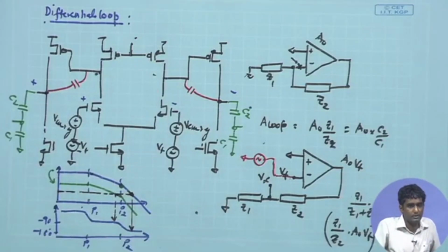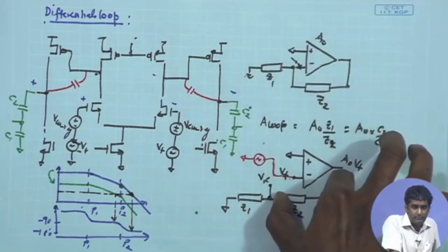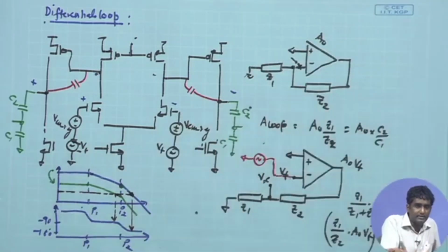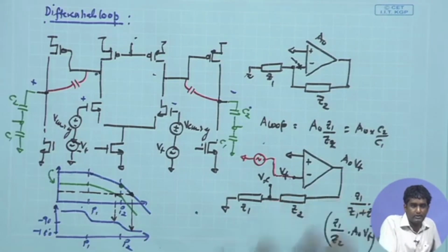How will RF affect the low frequency region, like you told now, it will behave as a high pass filter? So, we have discussed, right. While determining the value required for RF, we looked at the high pass response because of RF and the C2 that you have, and that must be able to pass the desired signal, and that only gave us the value of RF, because this RF produces a high pass response. That is what we had looked at.